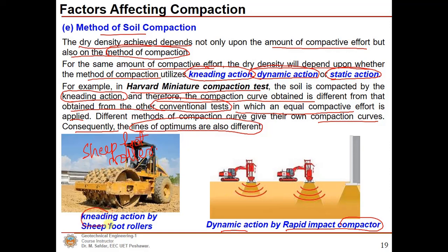Using the sheep foot roller, the kneading action, or the lugs or those feet, are used to squeeze and mix this cohesive soil, and usually vibratory or dynamic loading is preferred in granular soil to remove the air voids present in these types of soil.